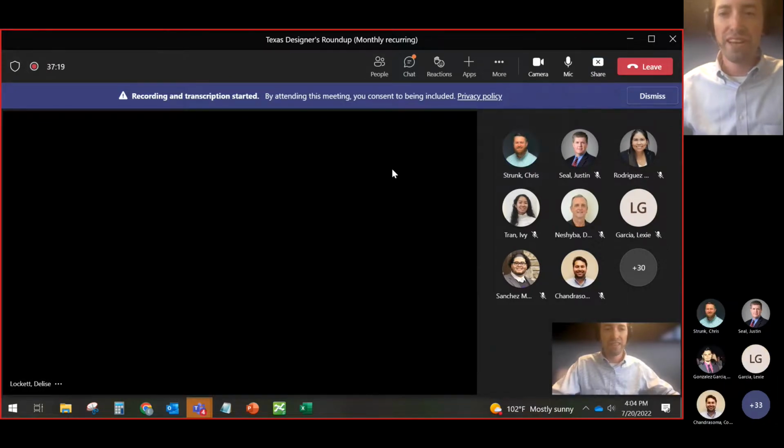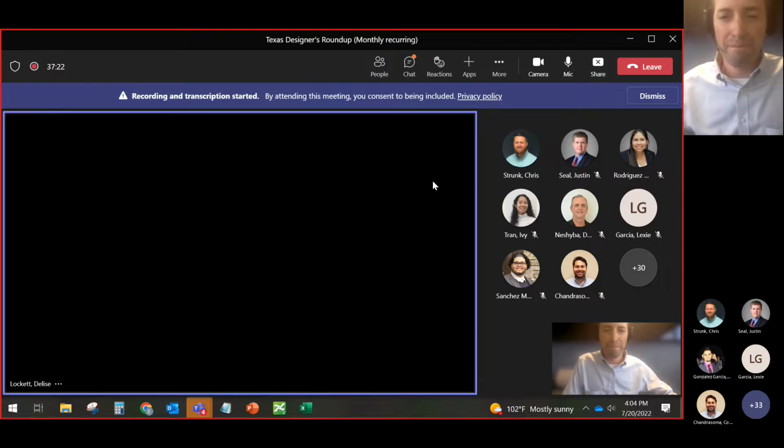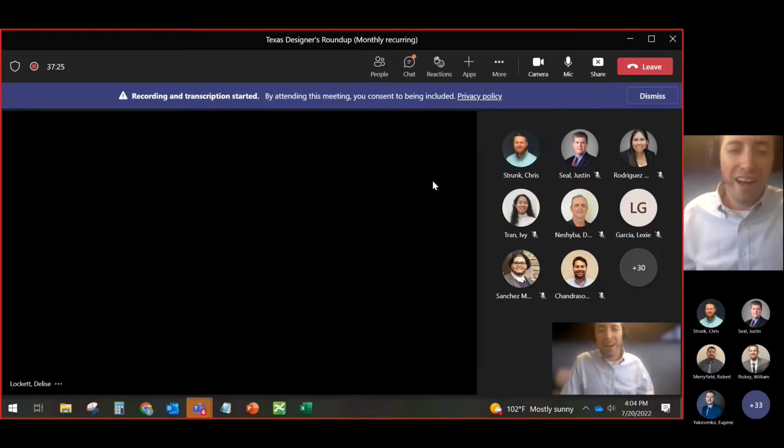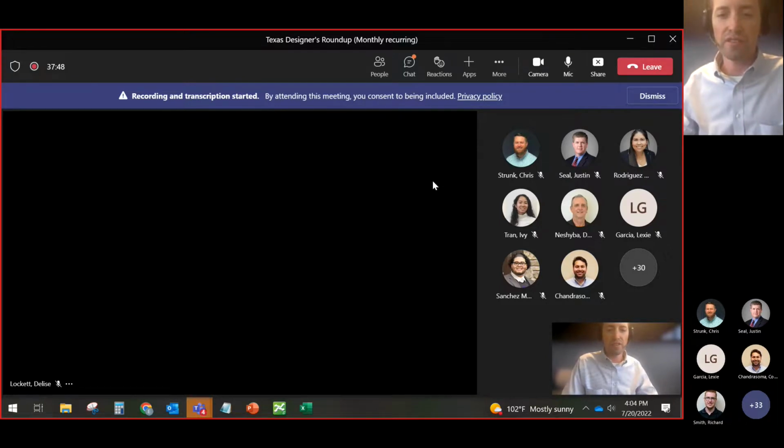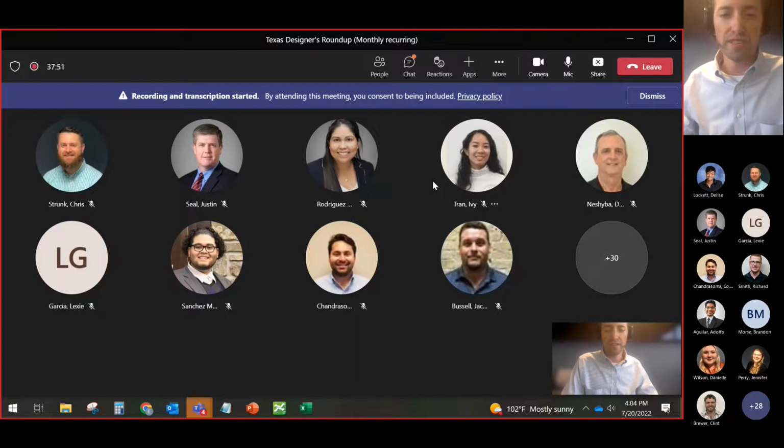Eric. Yeah. Who does the first pass at ditches? I don't really have a strong opinion on that. But if roadway does it, I want them to be thinking it through like we think it through, and thinking about, don't just allow geometry to automatically go off at a 4-to-1 and think everything's going to be okay. Really make sure we have positive drainage to the outfalls to save us time going through these projects. I think it can be done either way though, whatever makes sense for the project.